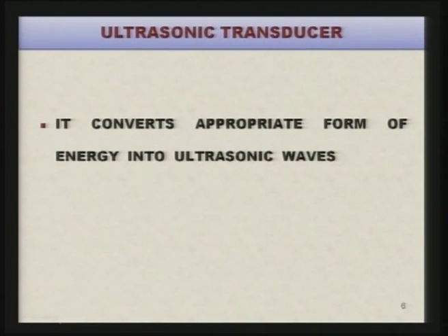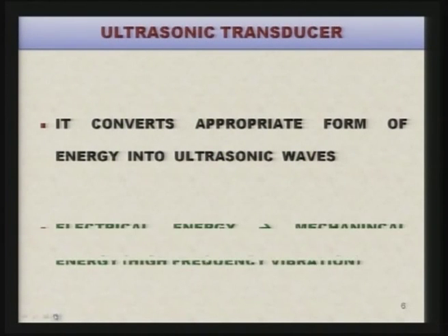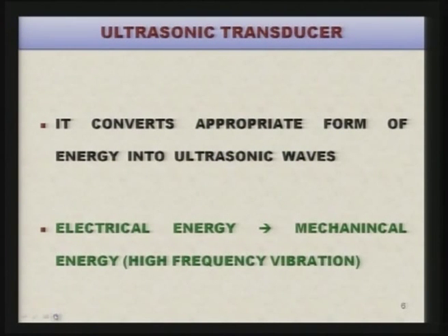Now, an ultrasonic transducer converts an appropriate form of energy into ultrasonic waves. Normally, in ultrasonic machining, electrical energy is converted into mechanical energy with a high frequency of vibration. Let us see what is the working principle of the ultrasonic machining process.